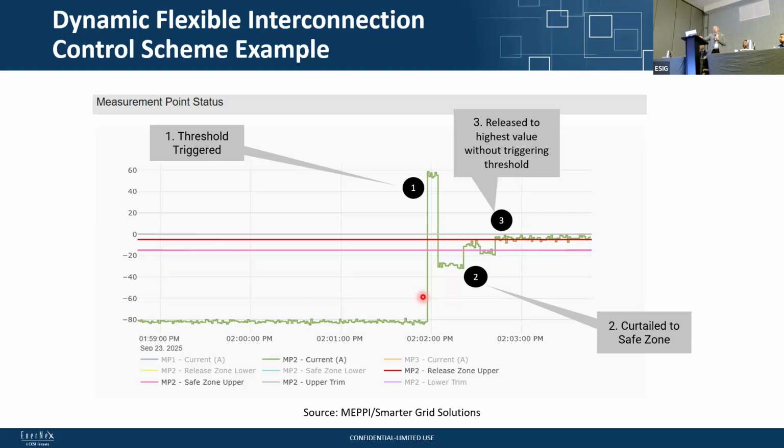Yeah. So it probably was. I don't know this specific case, but I'm pretty sure this would be a point on the feeder that it's monitoring, and it's been determined that this is a constraint point they want to look at. Again, something that might trigger this was a large load coming off, and now you've got overgeneration and you need to react. Does that make sense?